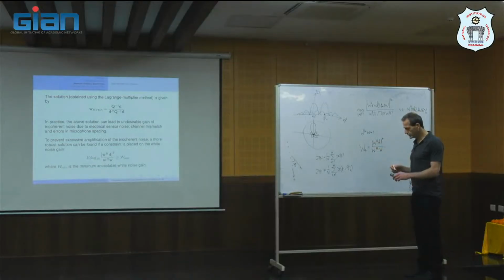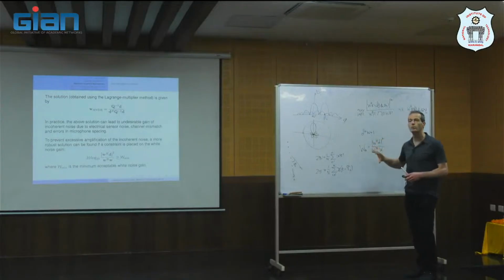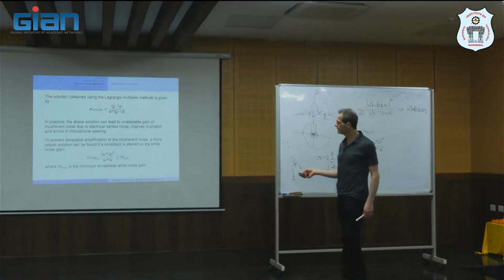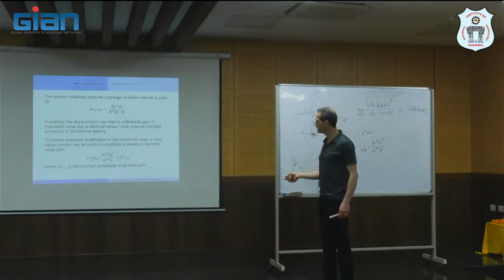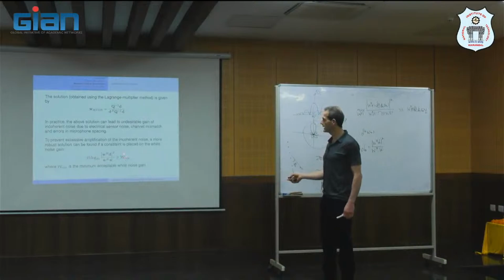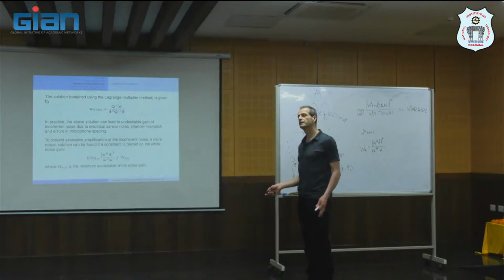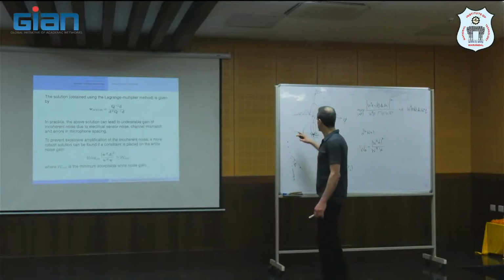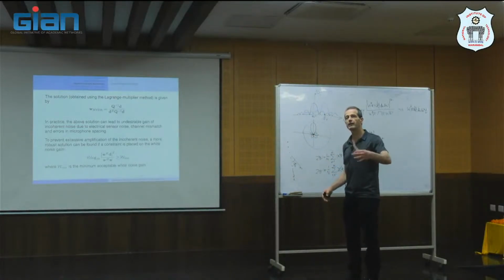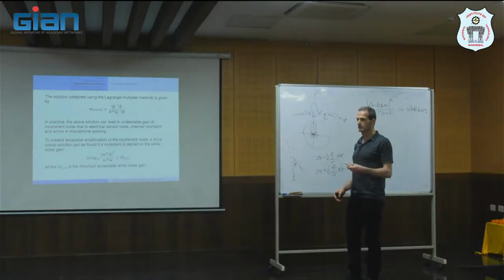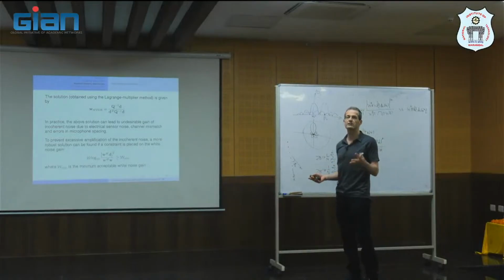And as I said, we don't want this to be too low for any frequency. So we need to limit it to be larger than a certain threshold, the minimum acceptable threshold. If it's, for example, minus 20 dB, it means that we allow the beamformer to amplify the thermal noise by 20 dB, so the thermal noise in the sensors is not too high.